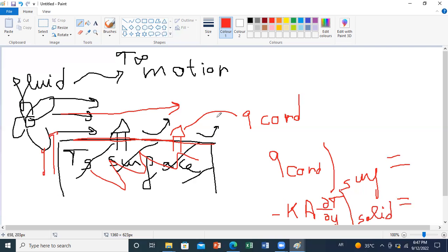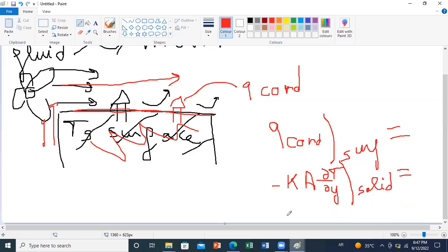The convected flux from the surface towards the fluid is equal to H times A times delta T. So the convected flux can be expressed as a function of what we call a convective coefficient, and this convective coefficient is defined empirically. So we do experiments to be able to assess H. In this chapter, we'll develop some empirical relations together and see how we can find H from experiments.